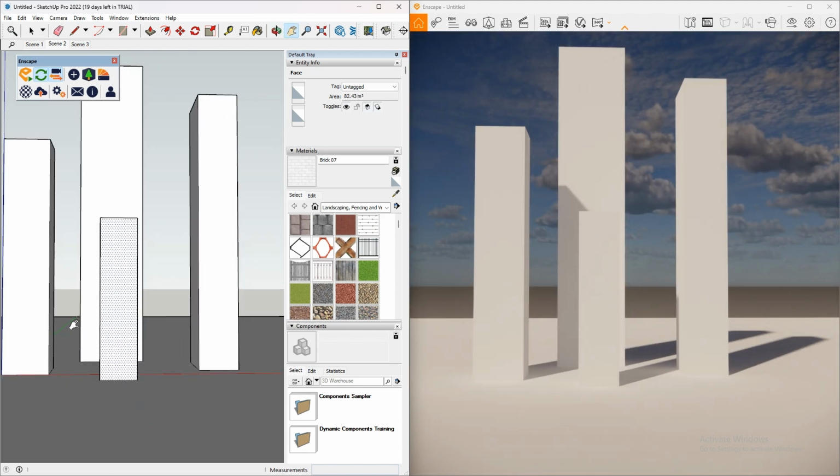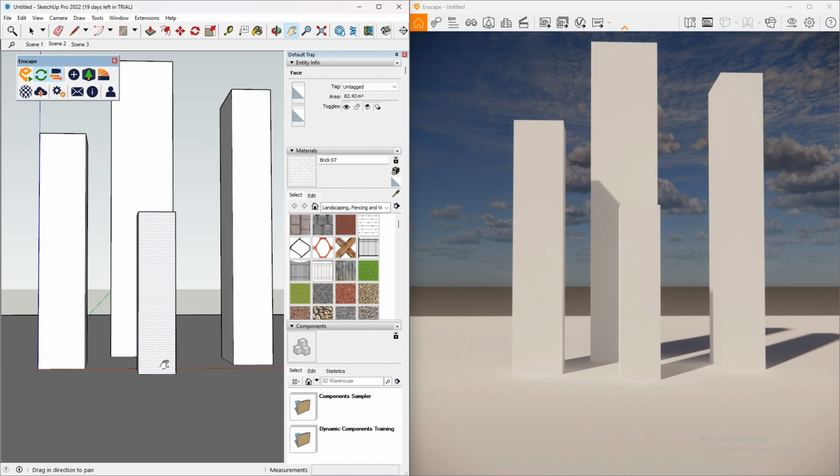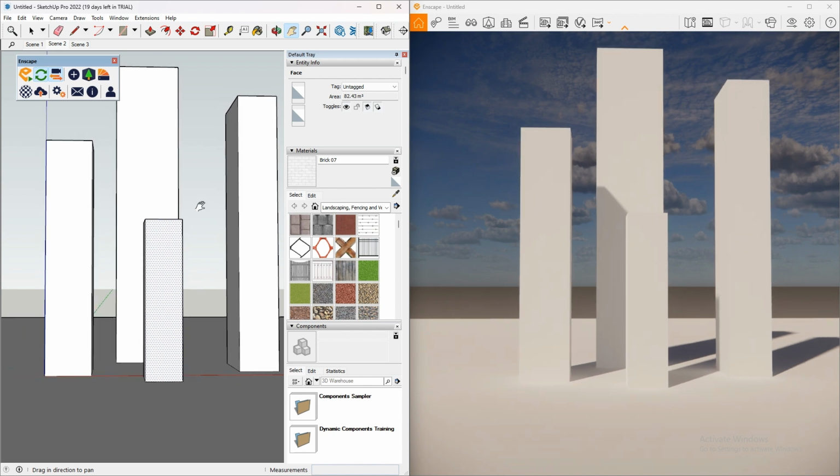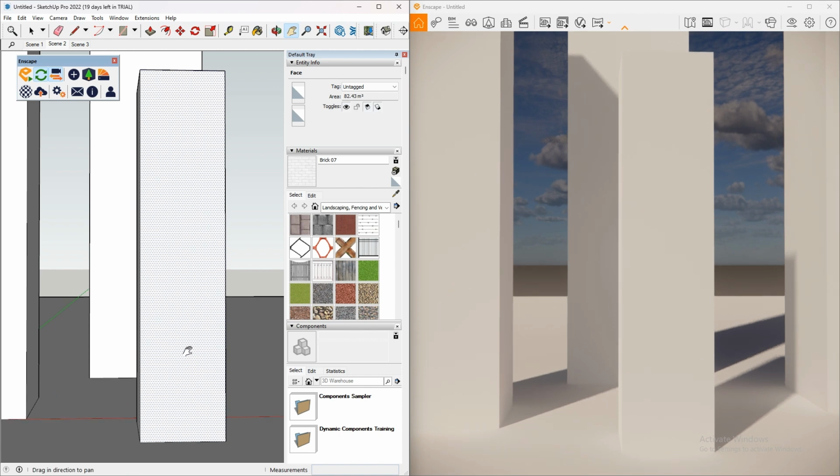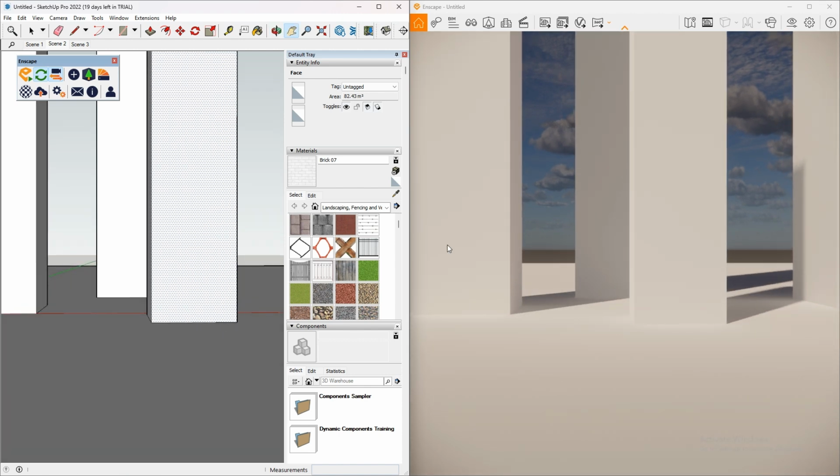The only downside about perspective is, and this is common knowledge, that to get more realistic renderings you want to have vertical lines shown here parallel with the vertical borders of your screen. So if I was to line it up right there and bring my camera down, that would be a realistic shot there.